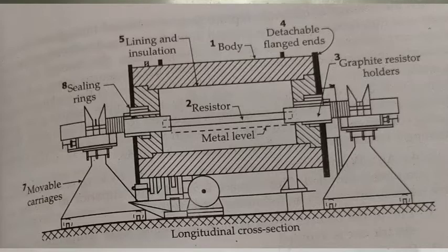Robust connections are made to the holders, and large flexible cables are used to carry the heavy electrical current, which is supplied from a special transformer with tappings on the primary winding, so that the voltage can be adjusted on the secondary to compensate for the increased resistance as the resistor wears. It is thus possible to maintain almost constant power input.